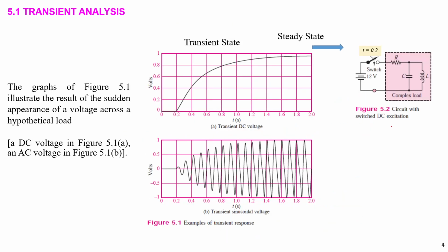And transient analysis comes only when we have storage devices, L and C. Okay, these will react to the system. As I talked about earlier, if we have the capacitor and we connect the circuit for a long time, the capacitor will get fully charged, and it becomes an open circuit.